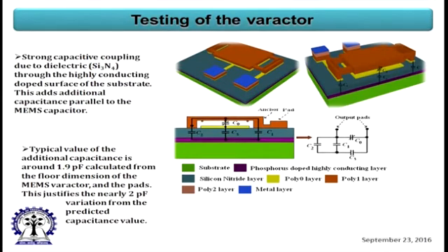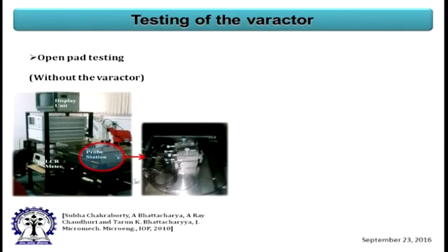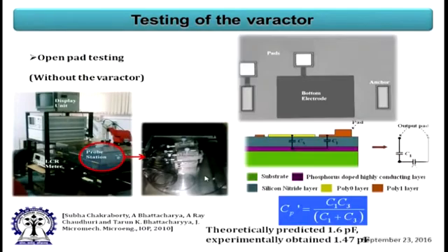To avoid this, we have probe stations where you can measure. I am also giving you a trick: in place of the device, you make a dummy structure and make the measurements on it, and then you subtract that capacitance from the capacitance obtained with the device, so that you de-embed the substrate capacitance and other parasitic capacitance to get the actual capacitance.